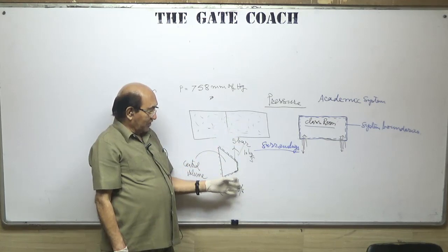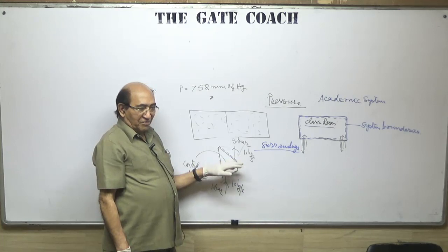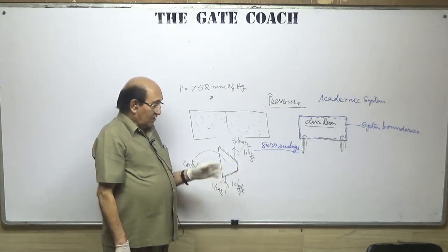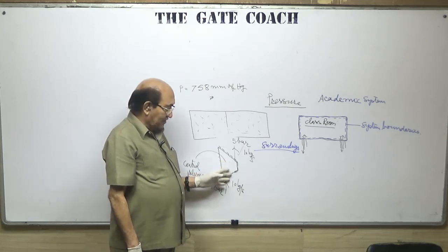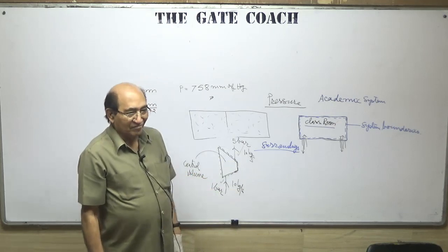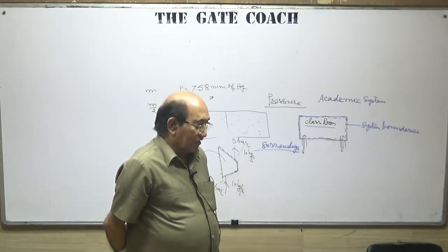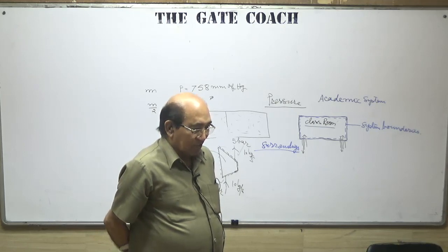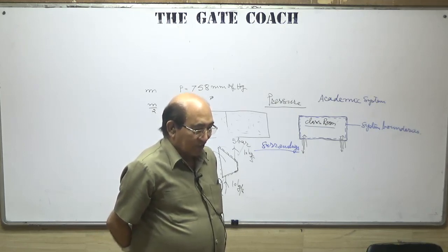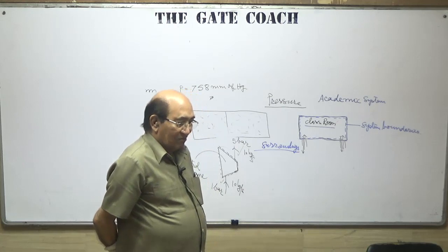Now you are putting a control volume, that means an open system. For example, I took air, which is compressible. With a little change in pressure and temperature, the density varies. So when you are talking of a control volume, density shall become extensive. When you are talking of a non-flow system, density shall become an intensive property.